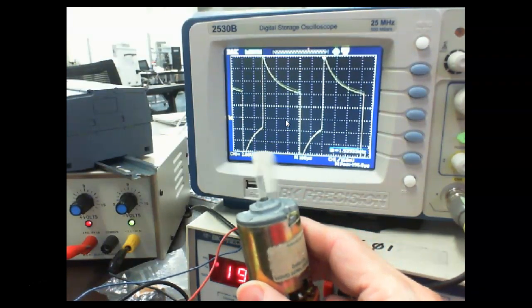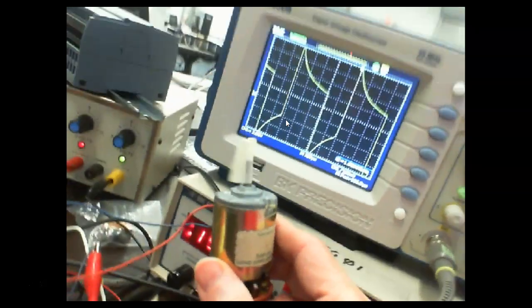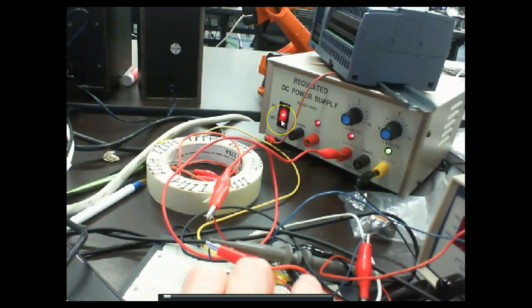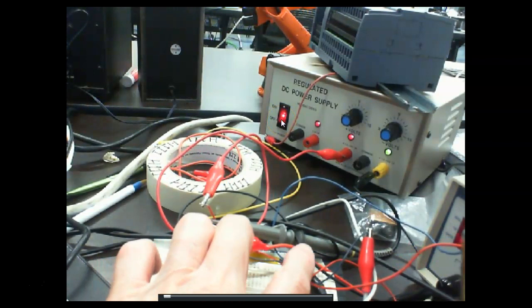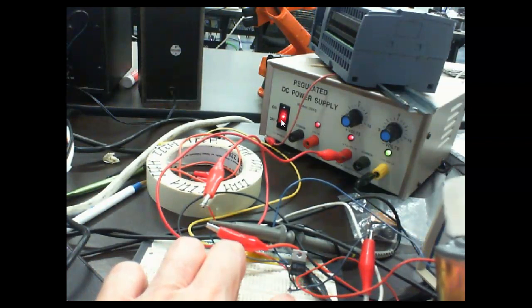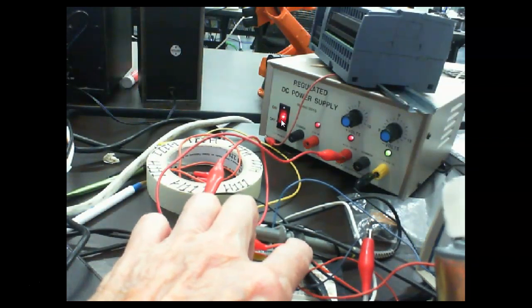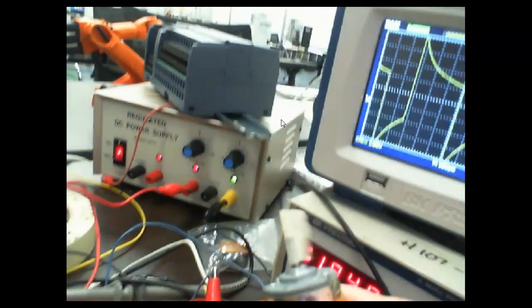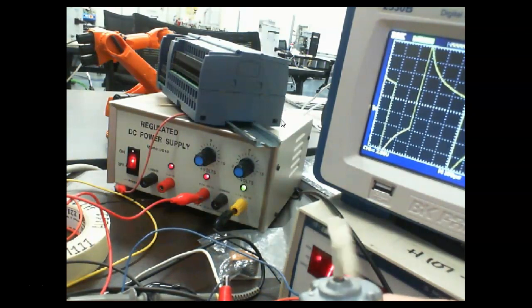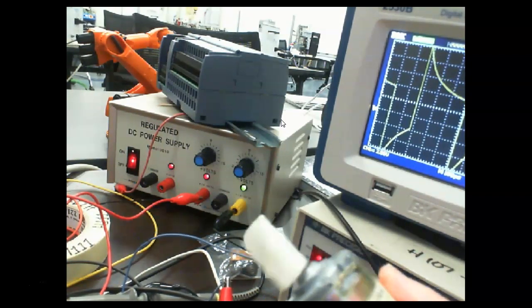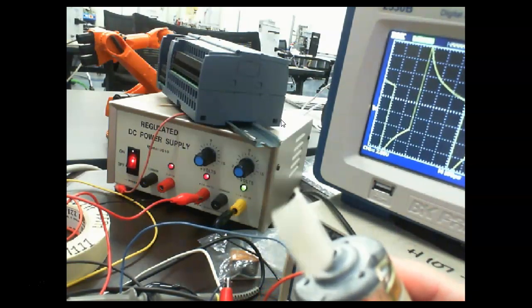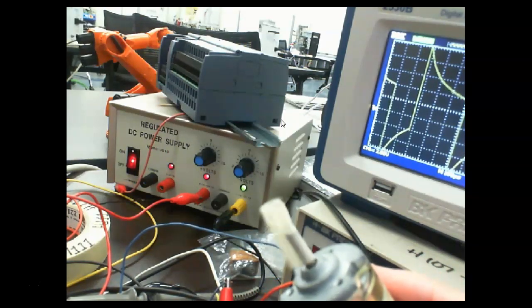Now normally you can hook this up to a drive circuit. My little function generator can't put that out. So what I have here is a transistor, an NPN. The function generator is controlling, turning this thing off and on, and the actual power is coming from this power supply over here. This is pulse width modulation that we talked about the other class, and they can combine pulse width modulation and actually create these variable AC drives by using negative and positive voltage.